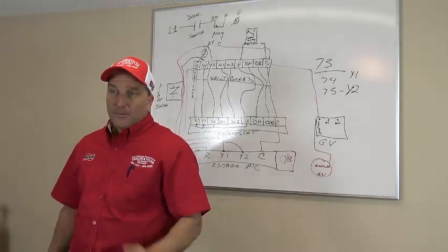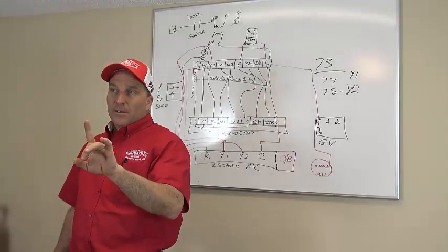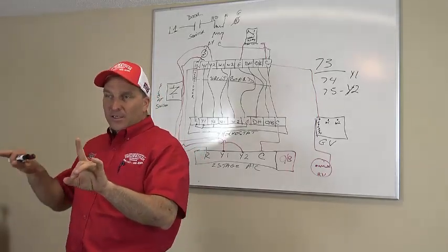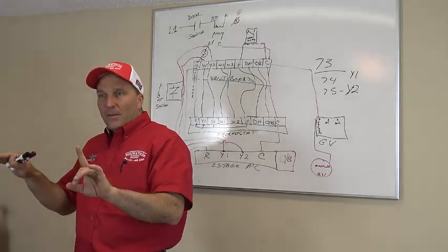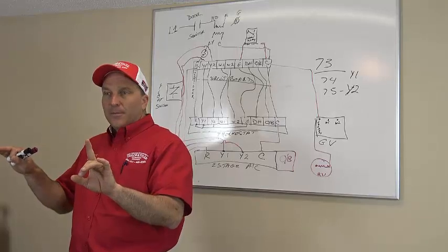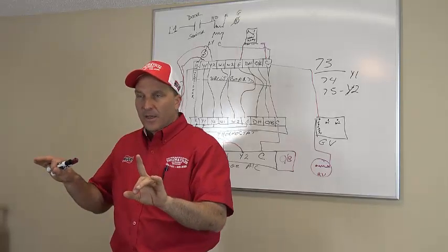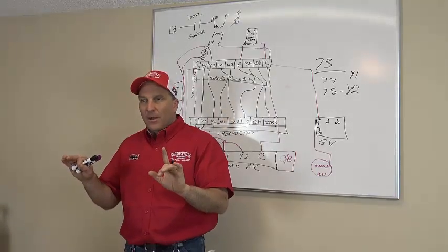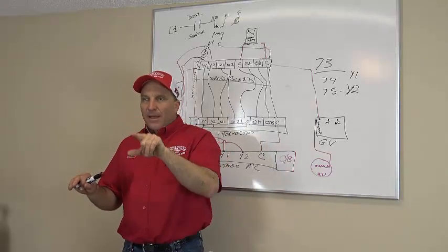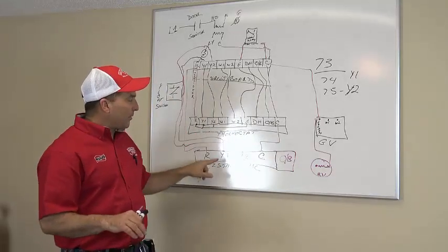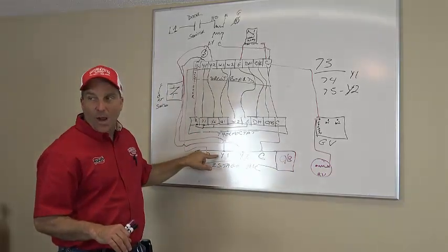Follow that? And remember, my G is on low fan, because it's a blower speed for filtration. You follow that? Did I lose anybody? Good? Okay, so I'm going to say it one more time. R goes to Y1 on my thermostat. That goes straight to my condenser and energizes Y1 on my condenser.